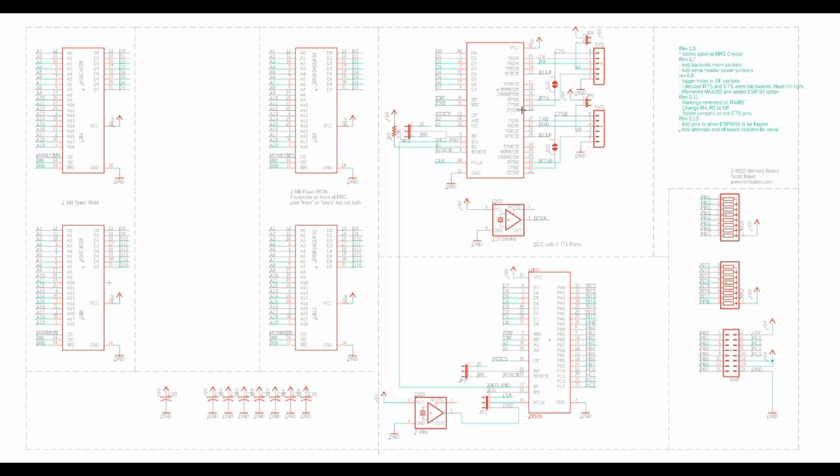Then over here, we have the serial ports. I put serial ports on the board using the Zilog SCC chip. Again, the Clover computer video will take you all through this, so we don't need to go into a lot of detail here. Just know that this thing is interfaced to the data bus. It can be interfaced in 8 bits instead of 16. It uses odd numbered ports, so again, we've ignored the A0. And it has 2 serial ports, one of them here, one of them here.